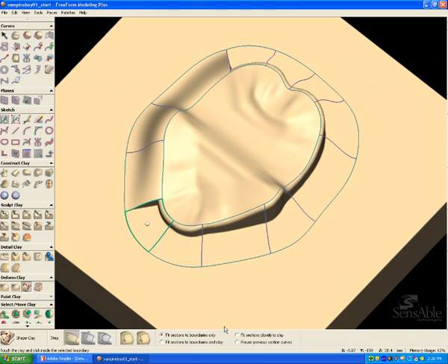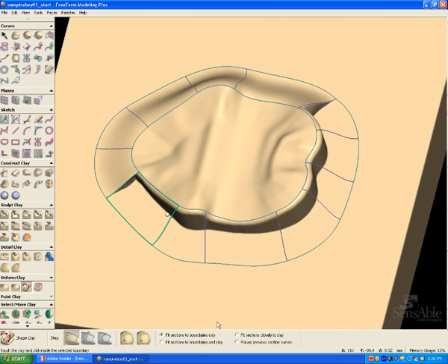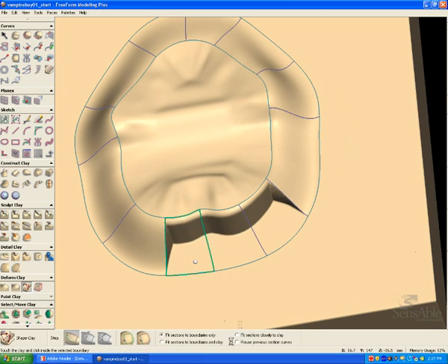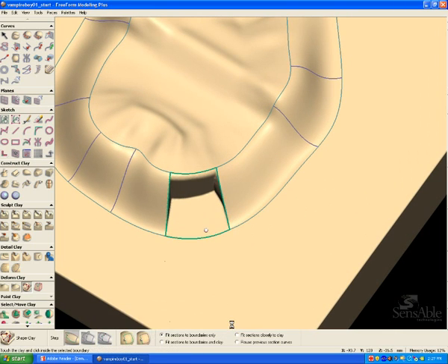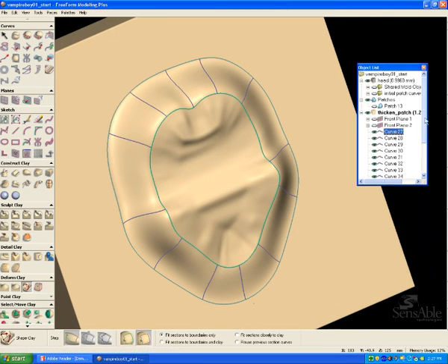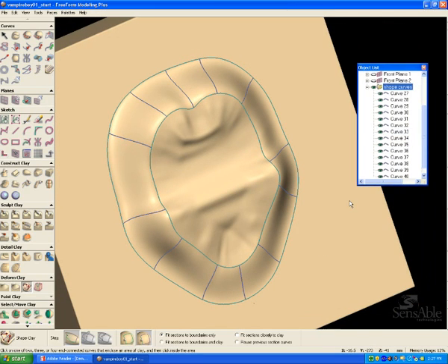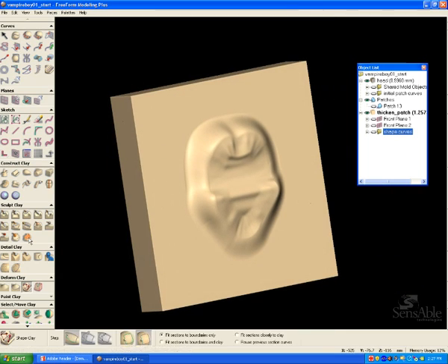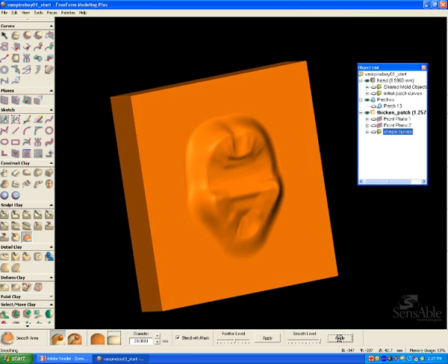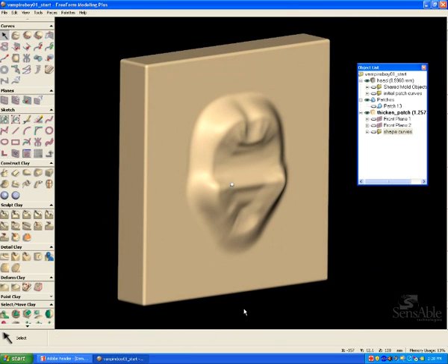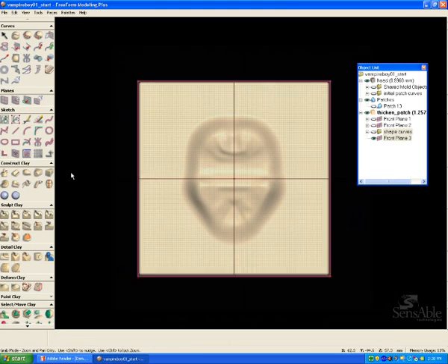That's a very important part in the manufacturing process, the ease of creation when it's being manufactured. So what I'm doing now is I'm using the shape tool to create these new transitions, these new transitionary surfaces between the complex part and the flat part of the clay. And I'm doing them separately because it's a lot easier to get an accurate part when you do smaller areas of clay. And what I can do now is I can give it a nice smooth once over, smooth the entire part to make the transitions that much better.